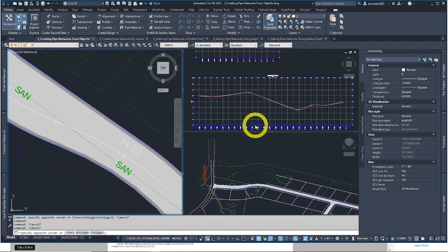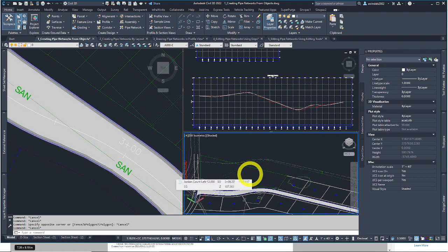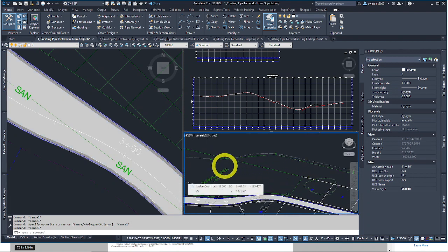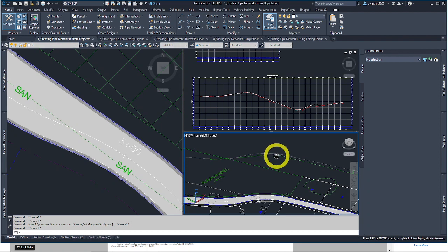Basically, on the left viewport, it wants you to pan southward until you can see Madison Lane. We'll do that in a second. Also, in this bottom right viewport, be very careful with this one. It's easy to get crashes. You can see it made some pipe networks here off in space. They have certain elevations. There's the pipe. The structure is in the middle here.